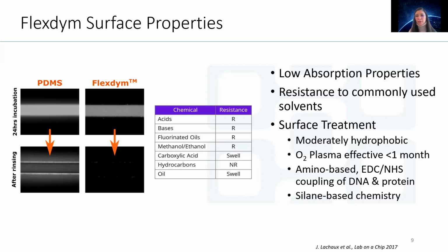Now, when it comes to the surface treatment, Flexdym, like many of these other materials, is moderately hydrophobic. However, it displays an incredible hydrophilic stability once it has been treated with oxygen plasma. And this can last anywhere from 1 week up to 1 month, depending on the specific storage conditions of the device.